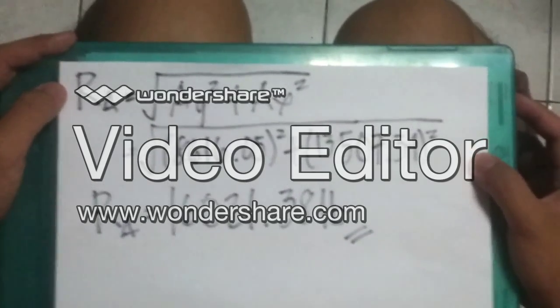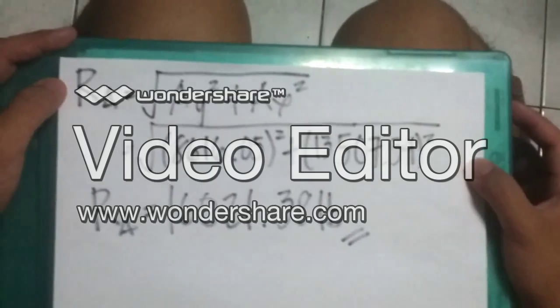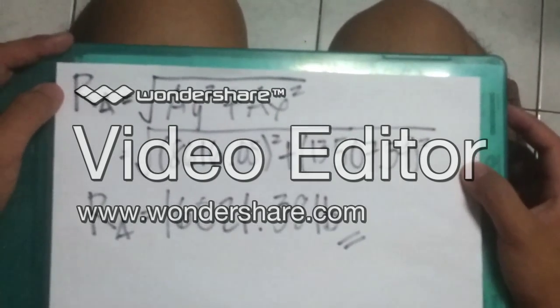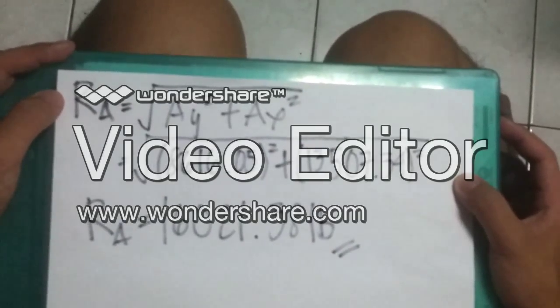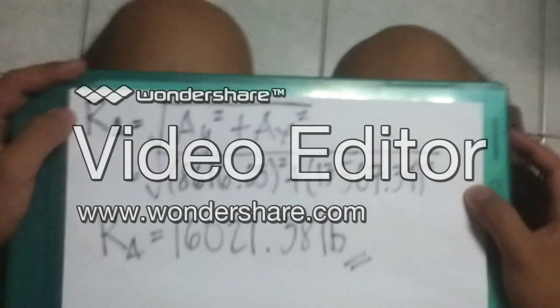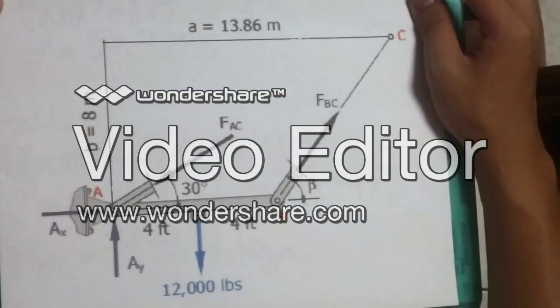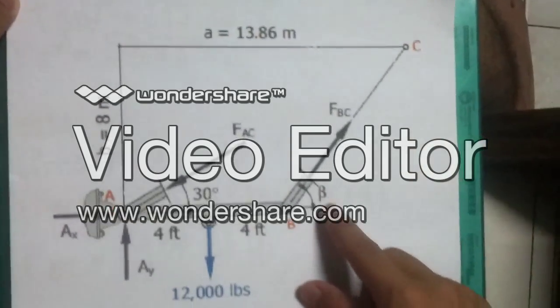Finally, to compute the reaction at point A, the square root of AY squared plus AX squared, or the square root of 8,616.05 squared plus 13,507.34 squared. So the reaction at point A is equal to 16,021.38 pounds.